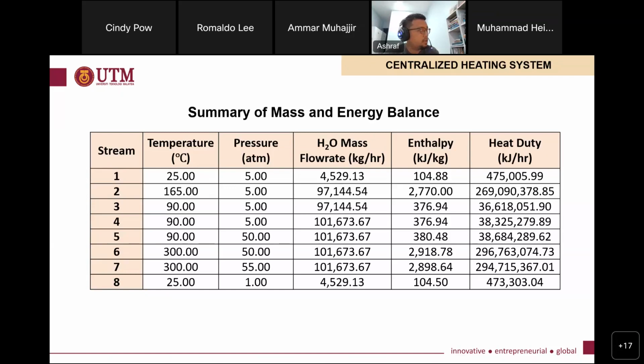So meaning you're considering your boiler is 100% efficient? 90. So if 90, because why I'm asking is just to confirm that you get it right in your cost analysis, so that you will be able to answer correctly to your examiner. The heat required is 258. When you consider your boiler efficiency is 90%, it's 258 divided by 90%. So your fuel equivalent should be 287 million kilojoule per hour, correct?